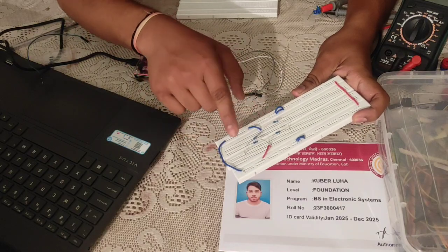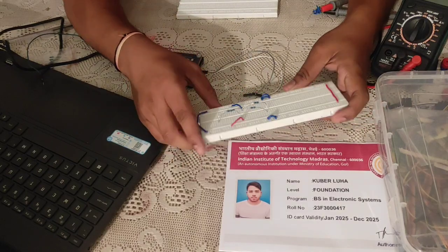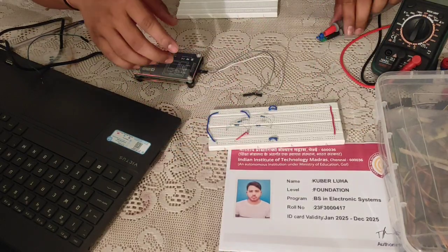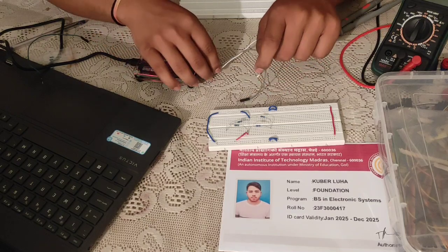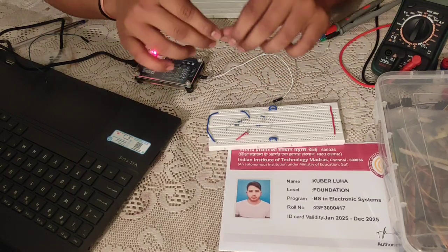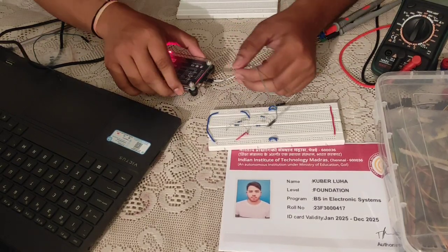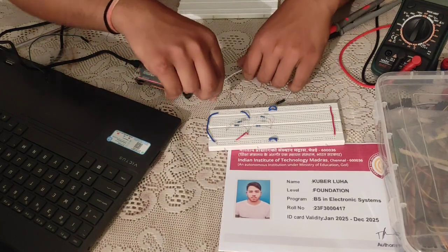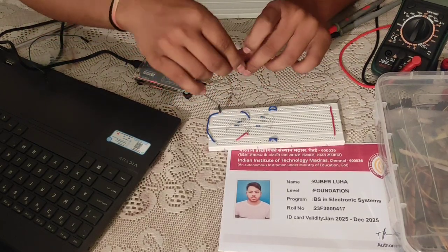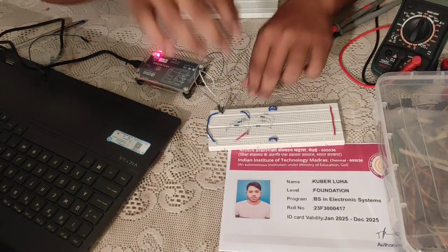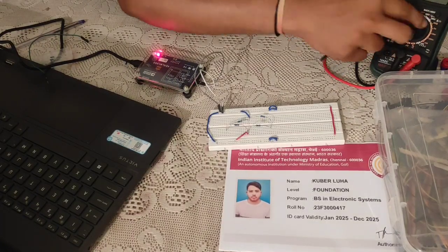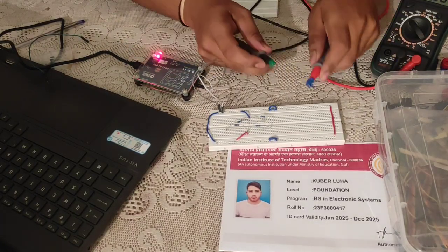You can see these are four resistors of 100 kilo ohm, and now I have to measure the voltages. First, I have to apply this excitation voltage from the ADLM kit. So here I connect this one to 2.5 volt, and this one is grounded. Let's do this one very fast. Now I have a multimeter, and I have to set this one to 20 volt and measure.